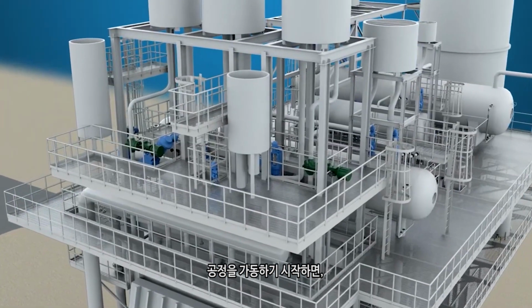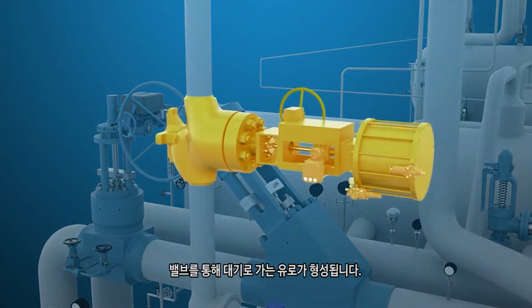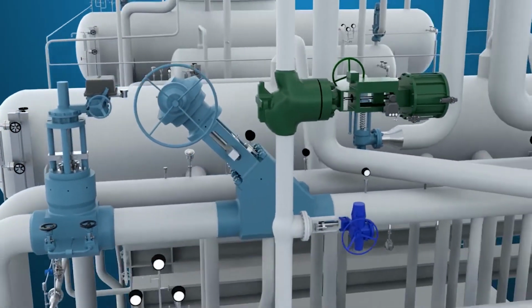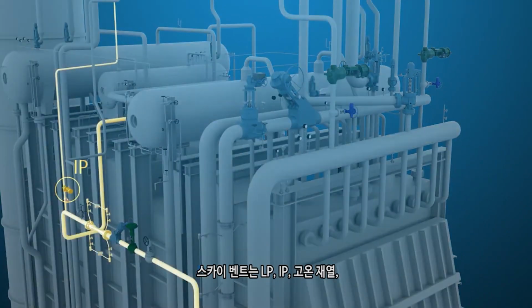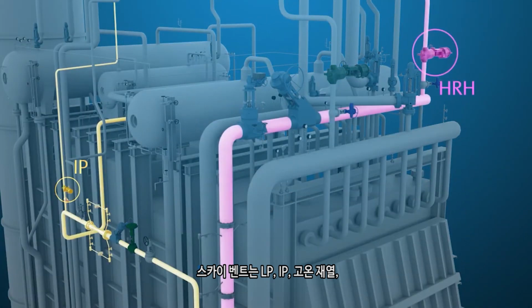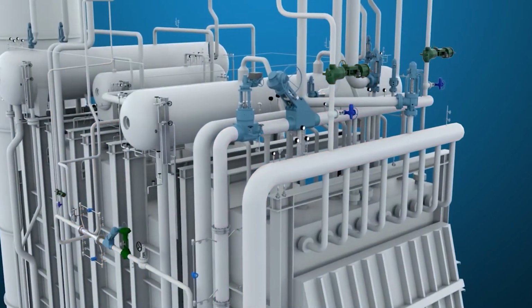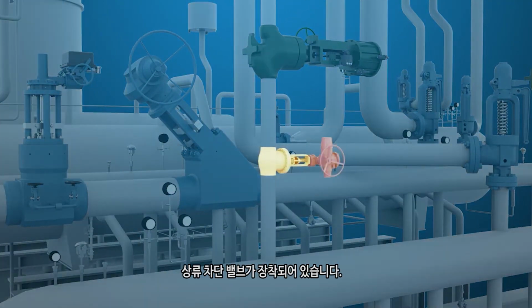During startup, a flow path is established to the atmosphere through valves called startup vent valves, or sky vents. The sky vents can be installed on LP, IP, hot reheat, or high-pressure superheater outlet piping. The valves are typically equipped with an upstream isolation valve, usually motor-operated.